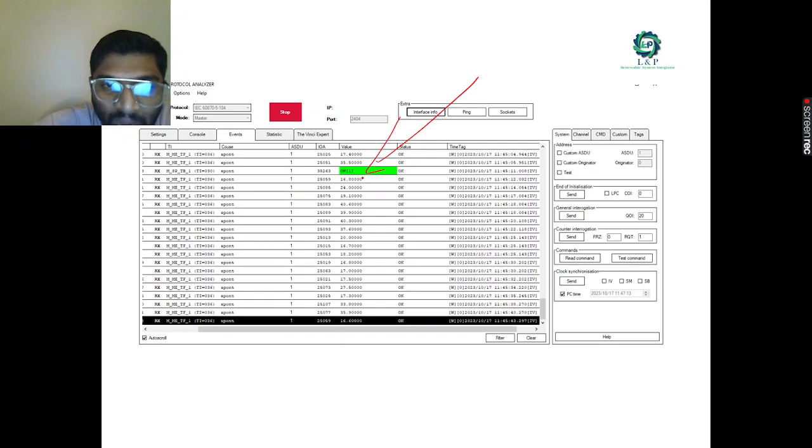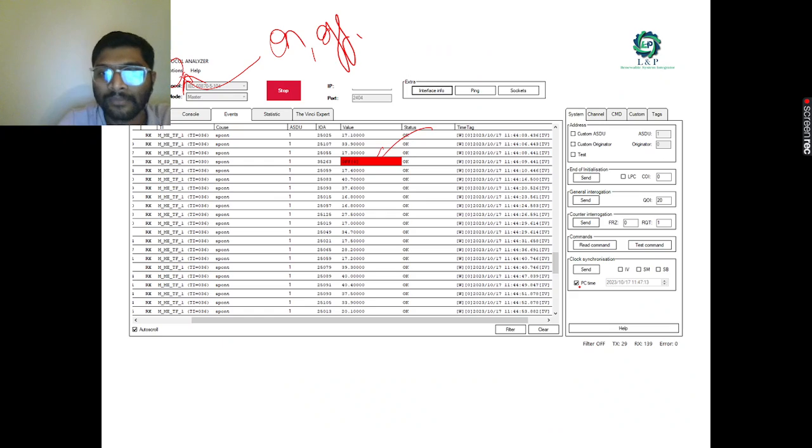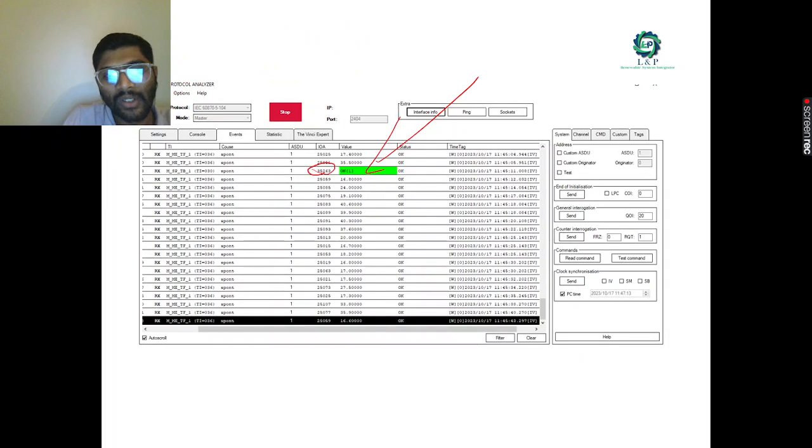As you can see in the event log, I am able to see the IOA address of the concerned equipment. This address you can see here in your gateway. Now it is turned on and off. Then I'm turning it on again, and the event is happening, so the communication keeps running. You might see that I started or stopped it because I just want to read the logs. Once the event happens, it will be there, and I can catch it immediately.